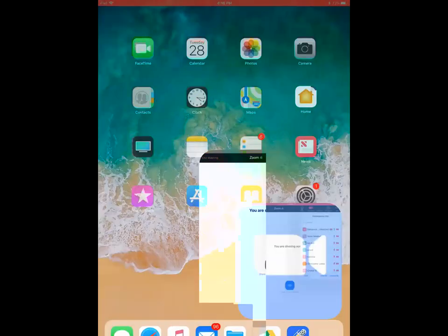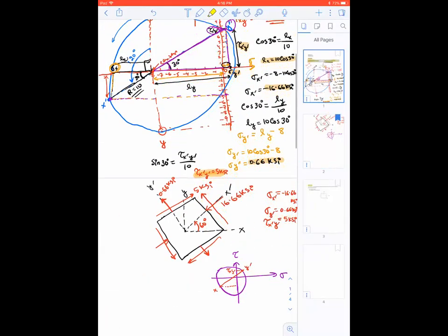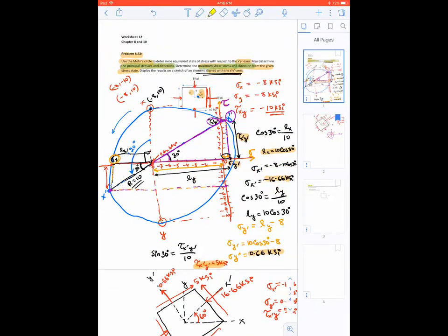If you look at my circle, it's too big. So it's better, I should have taken it as, you know, go to each side of the axis. I shouldn't have started 0, 1, 2, 3, 4, 5. I should have started 0, 2, 4, 6. So you get a smaller circle. And then the other thing is, remember, whatever axis scale you choose for your sigma axis, you choose the same for your tau. Otherwise, you're not going to get a circle even. So you cannot go 0, 2, 4, 6 on your x-axis and 0, 1, 2, 3, 4 on your y-axis. You want to keep it the same.